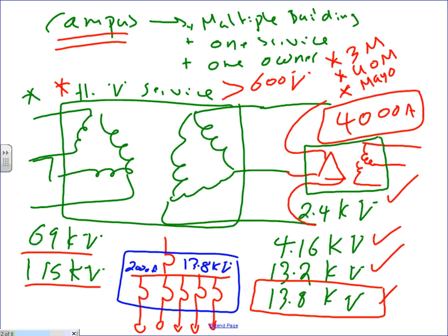At the bottom here, what they do, you take one feeder, you land it on a transformer like this, and that's where you get 480, 277, where you feed your building. You can't bring these lights at 4160 volt. You can't. So what do you do? You take the feeder to another transformer, step it down to most likely 480, 277, and feed it through your building. Any question, guys, about the primary service or high voltage service versus low voltage service?